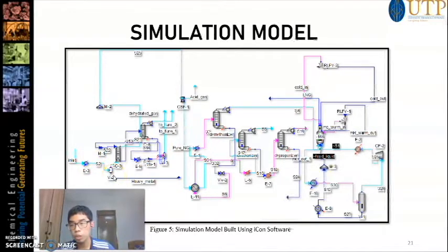After the removal of heavy metals, triethylene glycol was used to flush out excess moisture in the stream. Triethylene glycol was then recovered and introduced back as inlet of the absorption column. Then, the stream is passed through a high-efficiency membrane to remove acid gas, which consists of carbon dioxide and hydrogen sulfide.